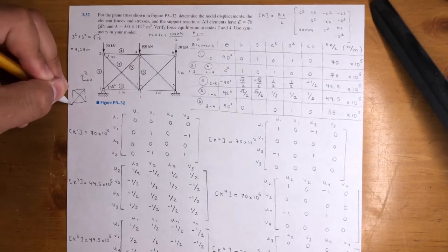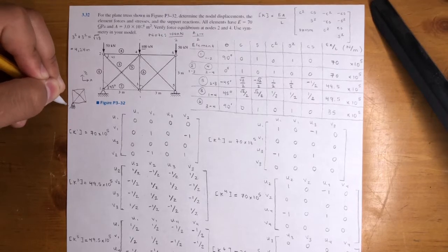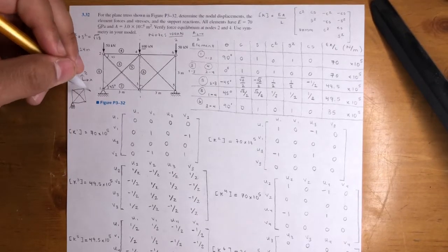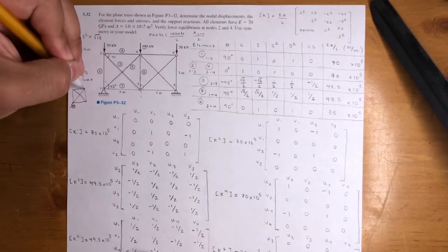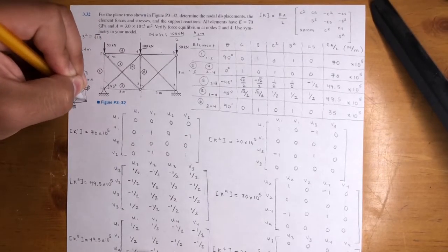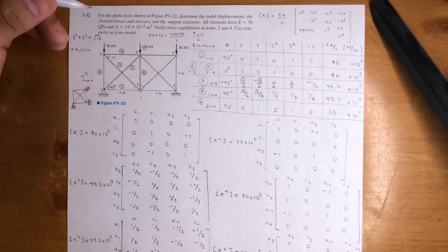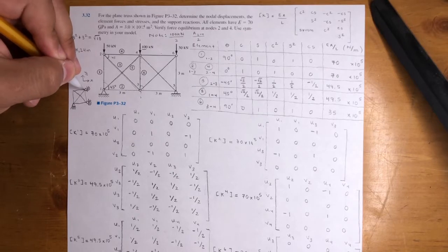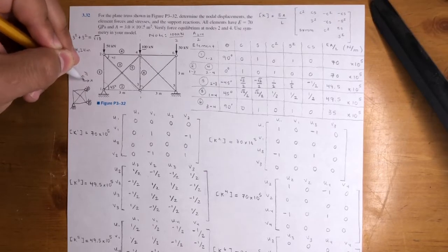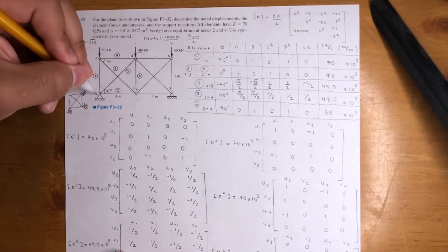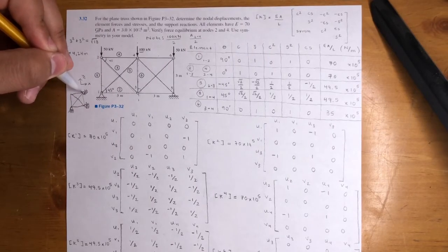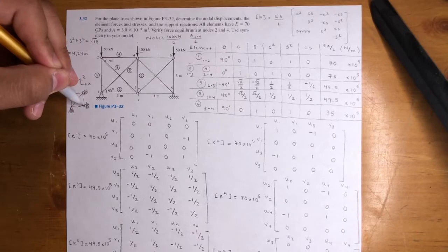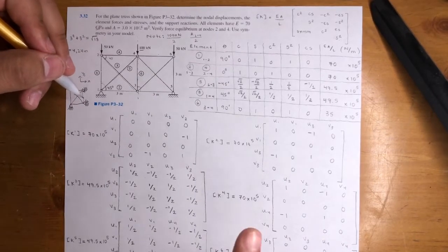But what happens is this is fixed right here, so there's no movement in the X or Y direction. But here, since you only have one force going down, you assume it's not moving in the X direction. So you make a roller. If you remember what a roller is from statics, I didn't remember until I looked it up maybe an hour ago, it only moves up and down. It doesn't move in the positive or negative X-axis, only in the Y direction. So apart from U1 and V1 being 0, your U4 at node 4 and your U3 are 0 as well. Not the V's, just the U's at 4 and 3.